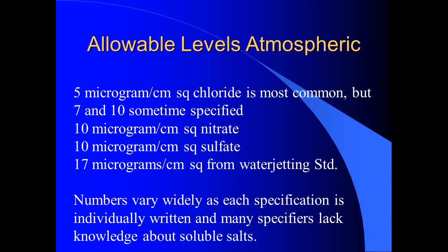They said, well, because some people want to be very careful to not overspecify and require too much money spent on surface prep. And I didn't say anything to her, but I don't care what you spend on surface prep, it's cheaper than a coating failure. A coating failure can cost you thousands of dollars per square foot to redo. I don't know of any original surface prep that costs that much money.